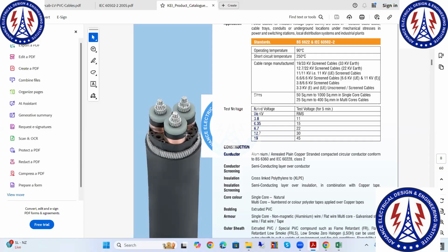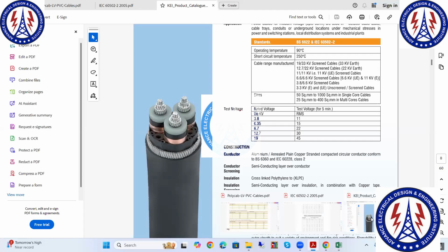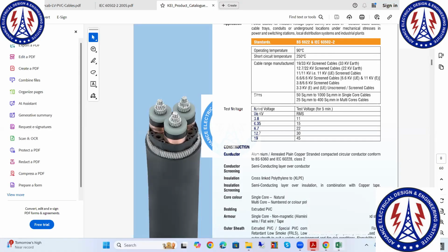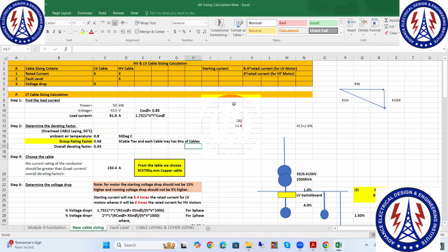Only single core cable, because in case of single core cable, if you are grounding at both ends, then a closed path will be created. Then that will once again reduce the current carrying capacity of the cable. So that is not recommended. We are grounding at one end only. Okay. Is this applicable for single core and multi also?